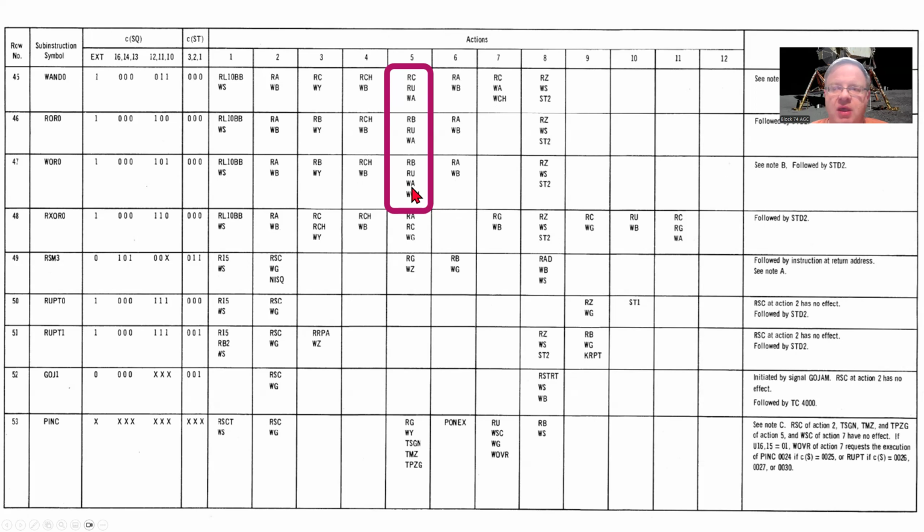So that's fine. One thing that we learned, and we had a little bit of a cycle back in one of the previous episodes, was whether this is an AND onto the bus or an OR onto the bus. We looked at the XOR, the exclusive OR function, when we were dealing with the A register. As we dug into it, and with some comments that came in from followers of the channel, the sub-instructions and the actions that take place actually use some Boolean logic to do the appropriate logical function.